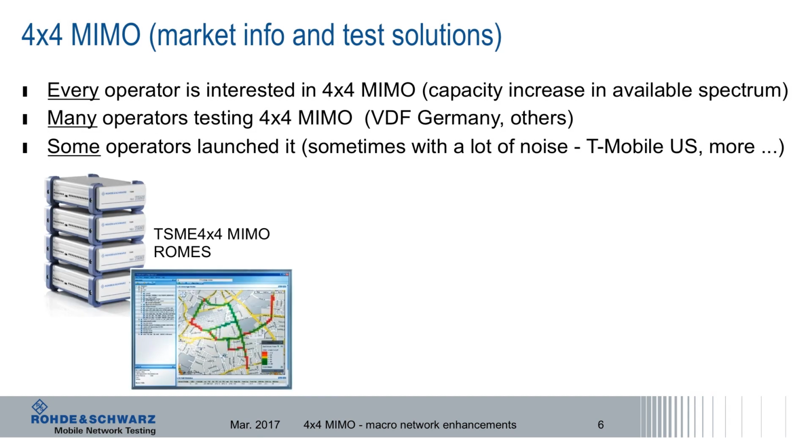So what are the test solutions here? We have to measure 4x4 MIMO, we have the scanner solution, a 4x4 scanner setup. So we have 4 one-channel scanners here, TSMEs, connected to the ROMES software platform for network optimization and troubleshooting.